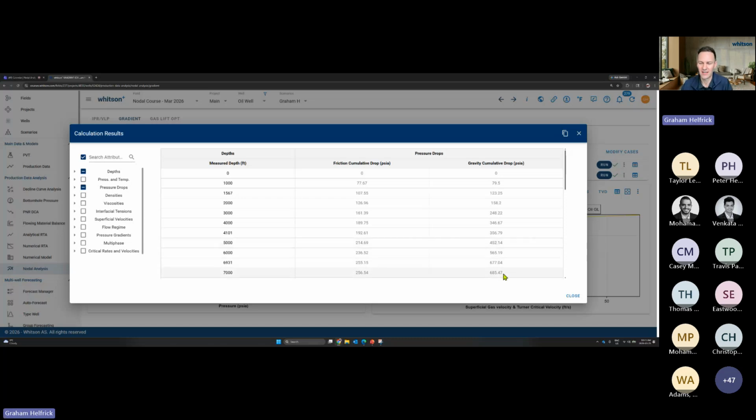But for gravity, I've reduced the pressure drop from gravity by 400 or 500 pounds because of all that extra gas lift. I basically made the fluid less dense because of gas lift. So this lets you dig into these effects and see why the bottom hole pressure is improved with gas lift. It's because we've reduced the delta P from gravity. We've reduced the density of the fluid.